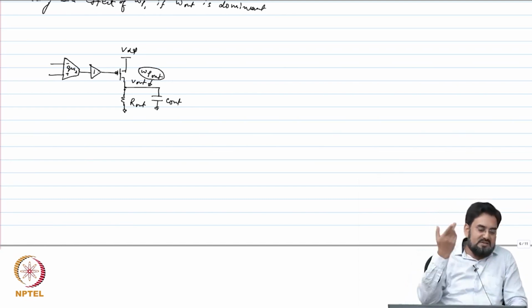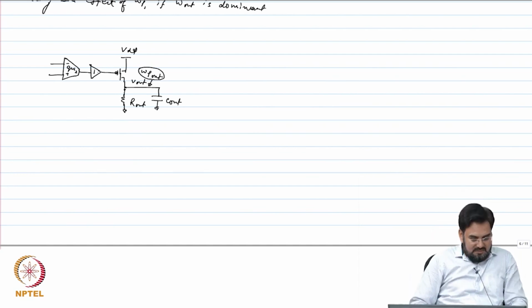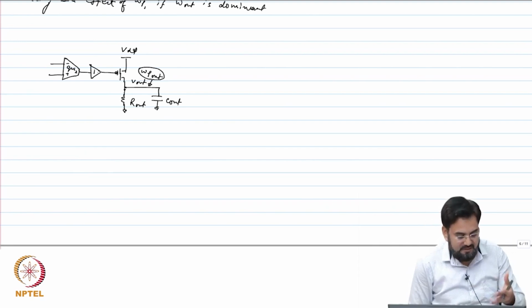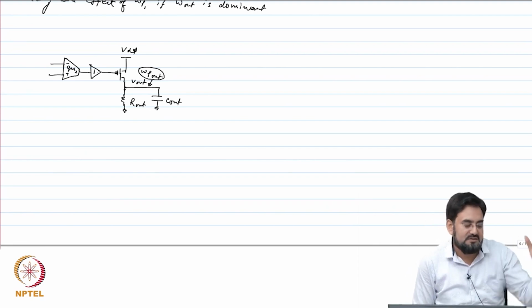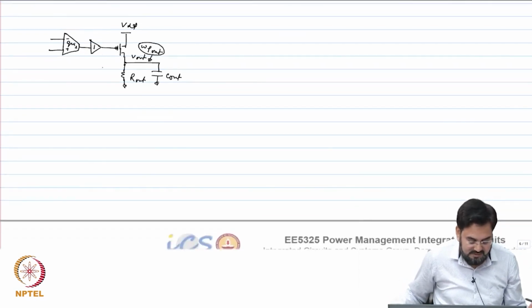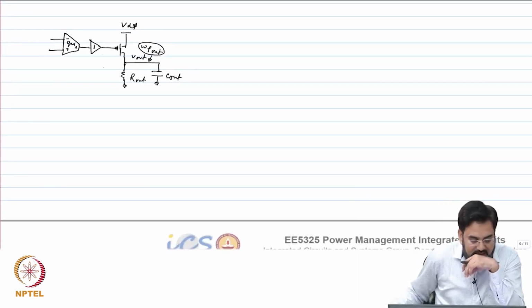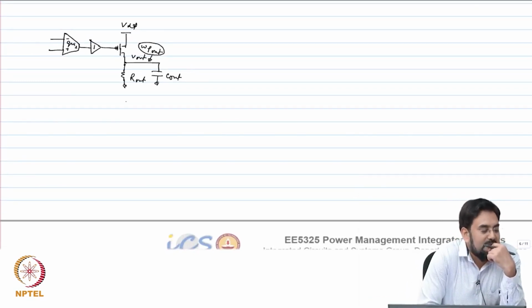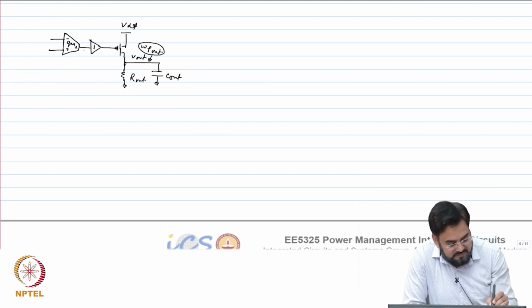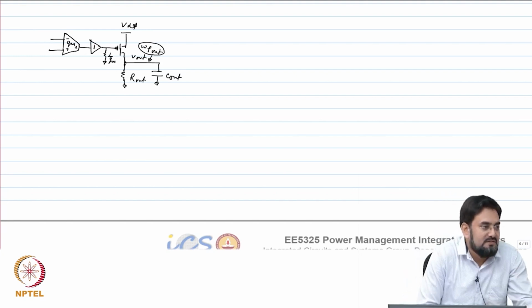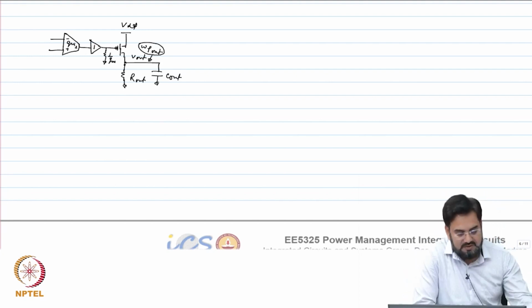Okay, and you can use the same source follower. Whether you use an N type or P type will depend on how your output signal is biased, depending on where it's getting biased. How can I reduce the gate cap? So this will become 1 over GM roughly, looking at the source of your output.